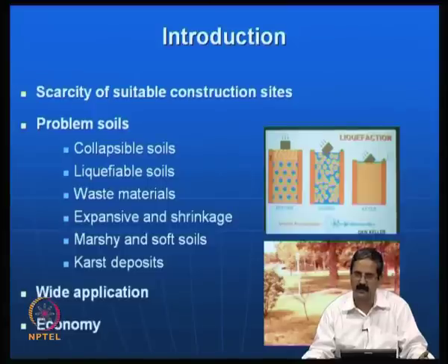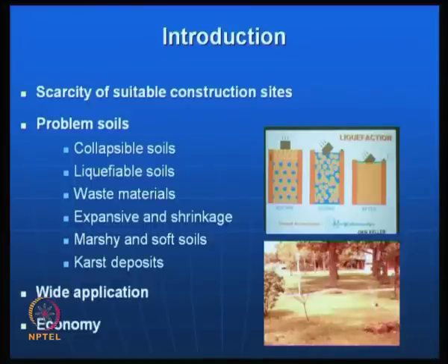So, you need to fill up those voids or gaps and see that the bearing capacity of the soil is there to the extent that we need, and also that settlements are minimum. So, the general applicability of ground improvement techniques is that we should have good shear strength, less settlements, and also permeability that will not create a lot of problems like pore pressures or seepage. So, we need to do a lot of engineering analysis here, and many of these techniques, particularly the ground